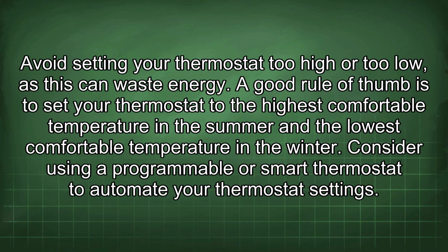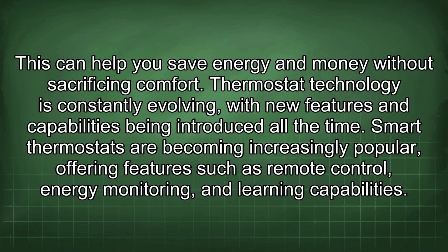Avoid setting your thermostat too high or too low, as this can waste energy. A good rule of thumb is to set your thermostat to the highest comfortable temperature in the summer and the lowest comfortable temperature in the winter. Consider using a programmable or smart thermostat to automate your thermostat settings. This can help you save energy and money without sacrificing comfort.